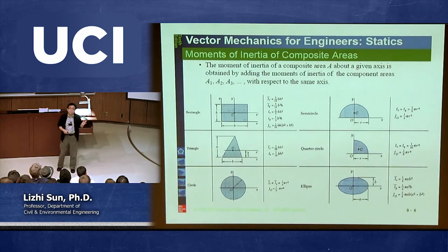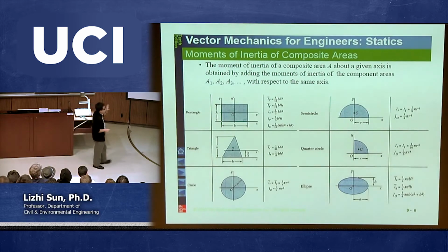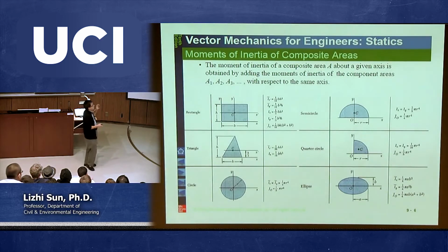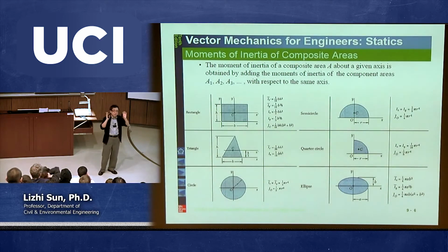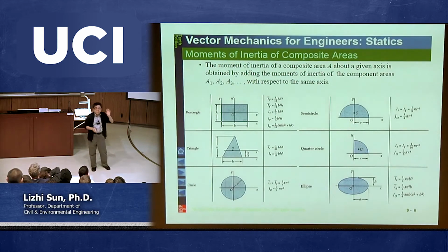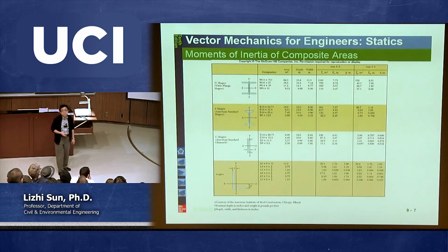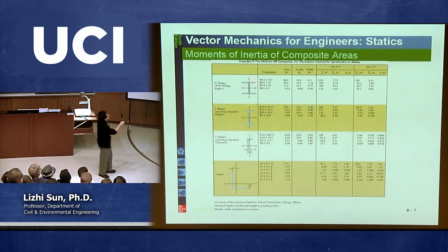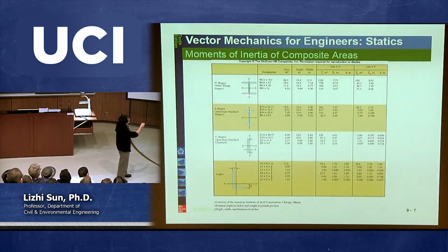But even that is not enough, because when we do engineering design, the most critical issue we are concerned with is the cost. So if I can design a slightly more complex cross-section area, using less material and yet providing a stronger moment of inertia, that's the best we can do. That's why later on, when you look at real beams in engineering practice, basically they are using these kinds of shapes. For example, instead of having the whole rectangular cross-section area, they use this, because what?